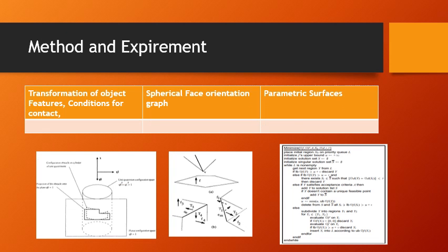In one, the problem is tackled in a radically different way: a trajectory connecting two arbitrary configurations for a moving polyhedron in a polyhedral environment is designed so that the obtained polynomials are of the lowest possible degree in 3 degrees of freedom. A polyhedral interference test is expressed as a combination of parameterized basic contact functions, these functions reflecting the spatial relations between the primitives of the polyhedra. The zeros of these functions delimit several time intervals whose combination, according to the interference test, provides the desired set of intervals over which objects would be intersecting if they were adhering to the predefined trajectories. While one uses parameterization based on quaternions, the other two allow the same approach using homogeneous coordinates.